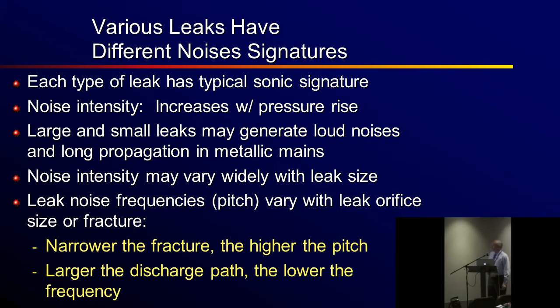It's a bit of an oxymoron. Leak frequencies or pitch will vary with the orifice size and the tightness of the fracture. The tighter it is, the higher pitch it is, sometimes the louder it is. As that fissure opens up a little bit more, the pitch goes down, less cavitation effects, more lower frequency, more of a roar. That's why the mains breaks have a deeper sound to it.